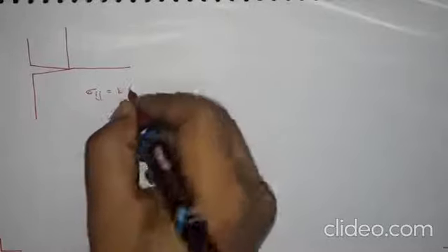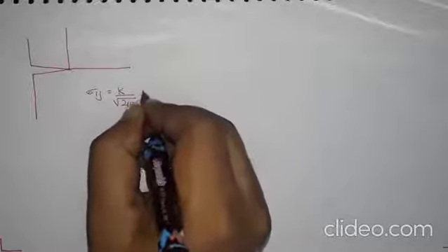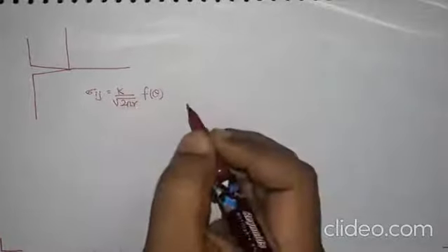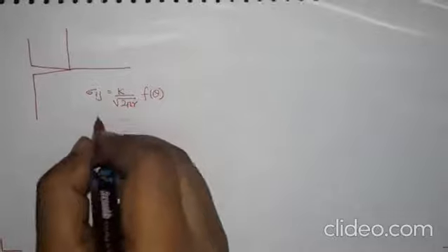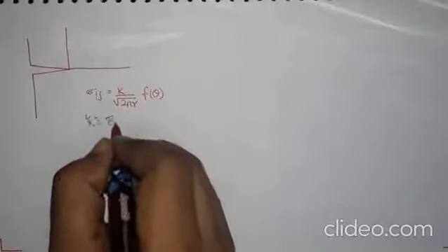We know now that stress intensity factor can describe the stresses at the crack tip. So if this is the crack tip, then stresses here can be described as sigma ij equals K divided by root over 2 pi r into f of theta. This K is the stress intensity factor, which is sigma root pi a,